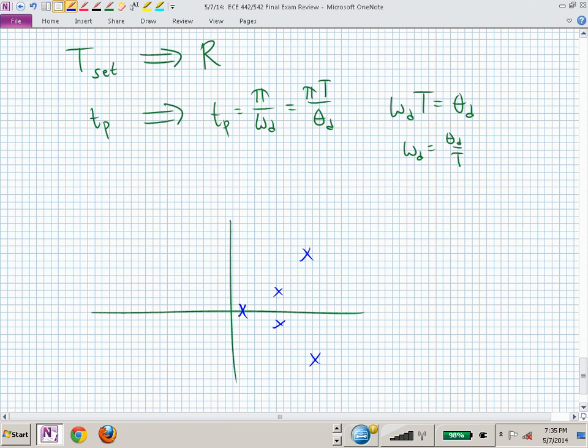Which of these poles would you use to determine what we've agreed to be determining, the settling time, peak time, and percent overshoot? Although it's not what's going to really happen because they all sing together. You now have a choir of 5 poles. Some are a little lower than the others, but we're concentrating on the lower ones here, aren't we? The dominant ones. Where's the dominant? Pardon? On the real?